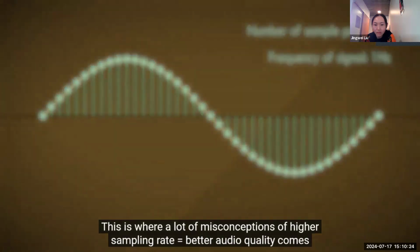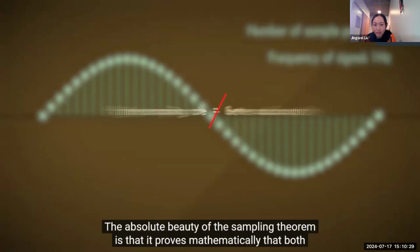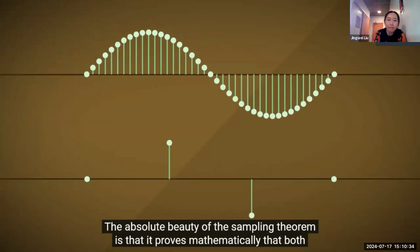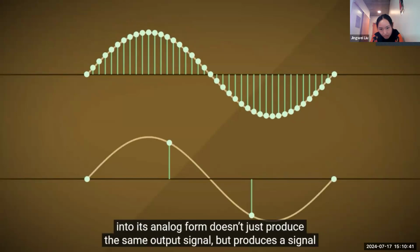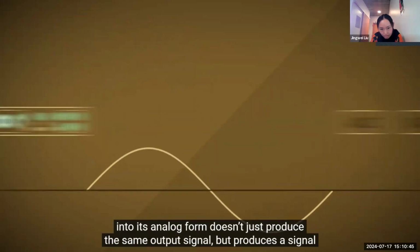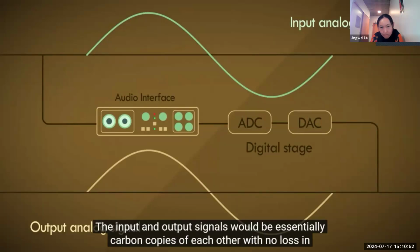This is where a lot of misconceptions of higher sampling rate equal to better audio comes from. The absolute beauty of the sampling theorem is that it proves mathematically that both 3 Hz sampled waveform and 40 Hz sampled waveform of a 1 Hz wave, when reconverted back into its analog form, doesn't just produce the same output signal, but produces a signal which is indistinguishable from the original analog input signal before conversion. The input and output signals would essentially be carbon copies of each other with no loss in resolution.